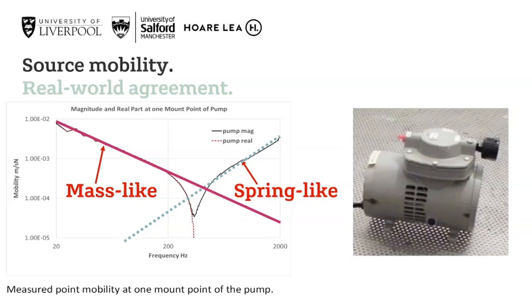Given the cantilever in this case is fixed to a source of interest, we now understand why we have two regions in the mobility response, and both are described well by the mass and stiffness equations. Whilst we don't predict the depth of the trough at the anti-resonance location, we know that we can expect one to occur as it roughly coincides with the intersection point between our two predicted curves.